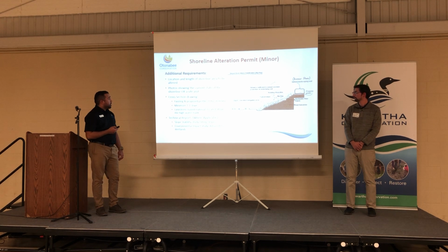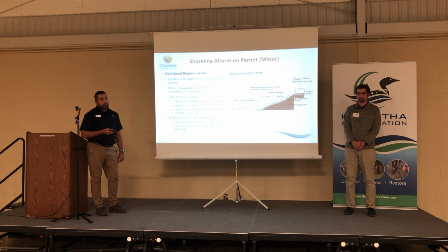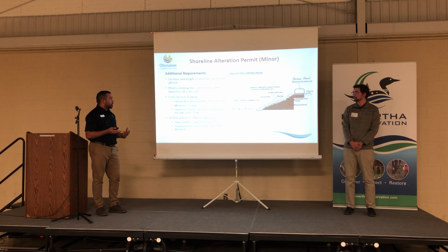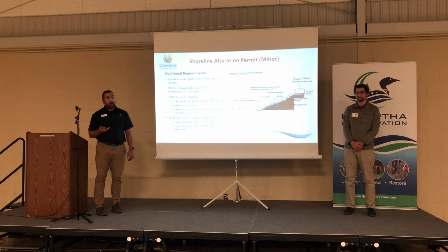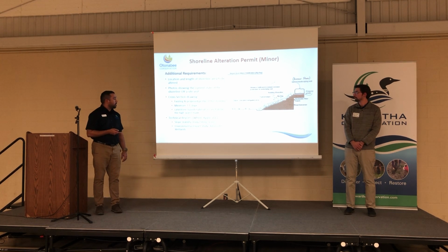On your site plan, you should also include the location and length of the shoreline area to be altered. And similar to Kawartha, we also do ask for photos of the current state of the shoreline, just to show how eroded it is and to show the need for erosion protection. If that's not possible, say it's winter and there's good snow cover, we can come out and do a site visit just to check on the status of the shoreline.